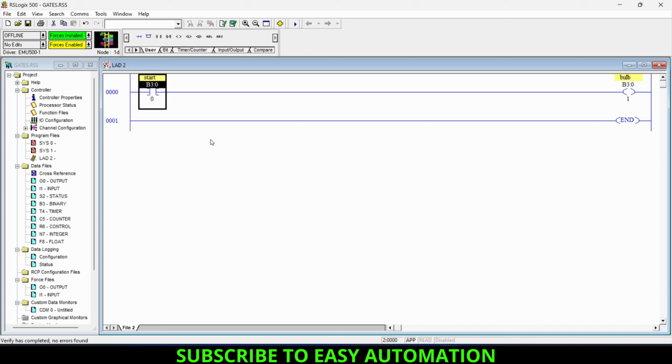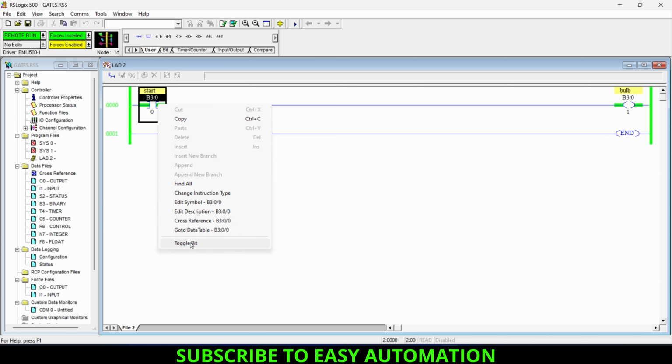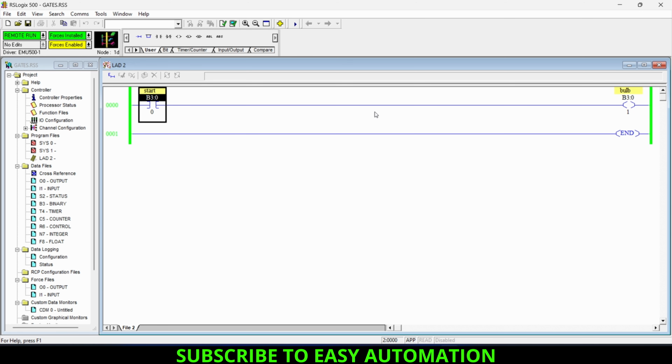So let's check. Our program has no errors. So now our program is in running condition. And if I toggle this bit high, then our output will go high. And if I untoggle this bit, then our output will also go off. So this is how you can use these memory bits for inputs and outputs in Allen Bradley.